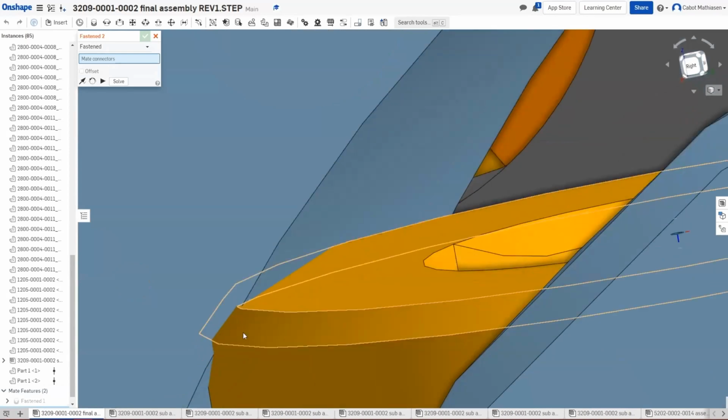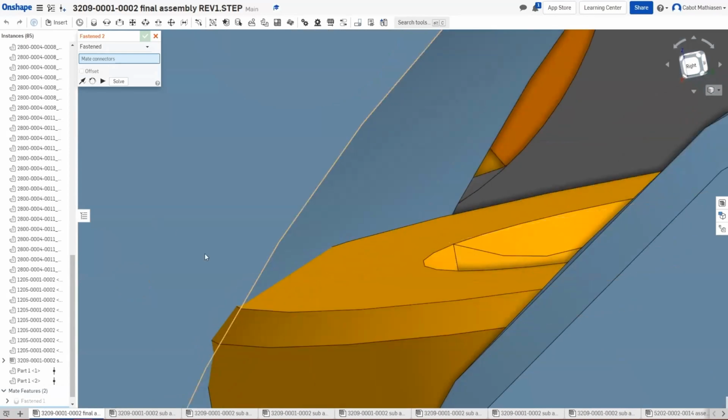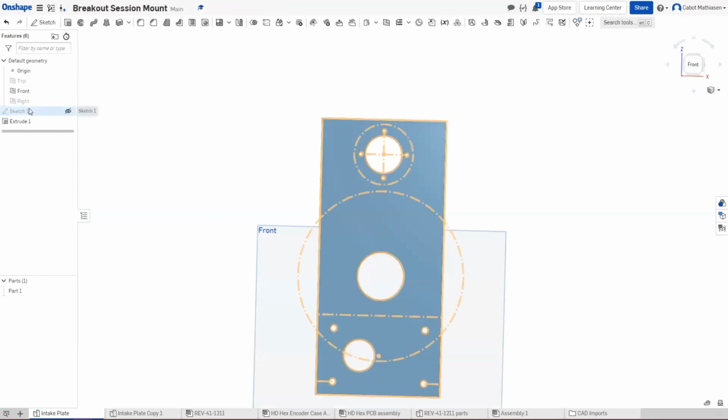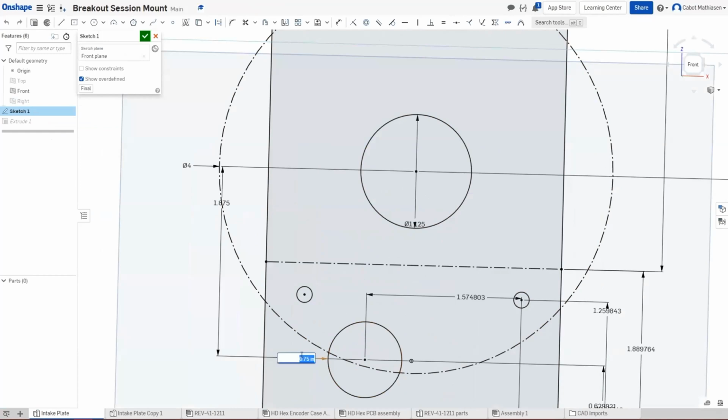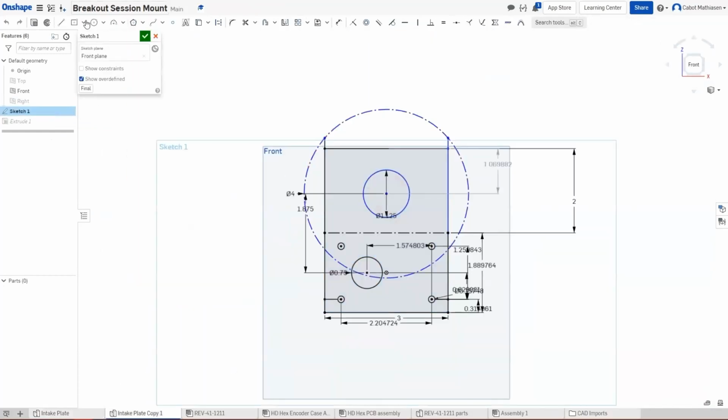As I said earlier, we can just go into the other part and edit it. We'll have to edit it on both. You right click on the sketch, you click edit, or use double click. So let's change it to 0.8, see if that works. Change it on both. So you type in the 0.8 again.